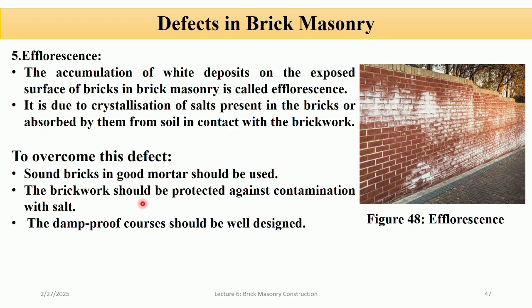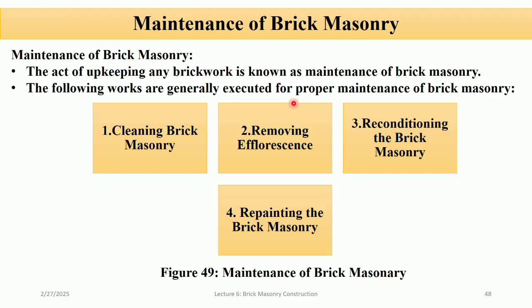The brickwork should be protected against contamination with salts, and the damp-proof course should be well designed, because the effects of the efflorescence are aesthetic issues, weakening of mortar joints due to the repeated salt crystallization, and increased porosity, making masonry more vulnerable to moisture damage. So we have to overcome this defect.